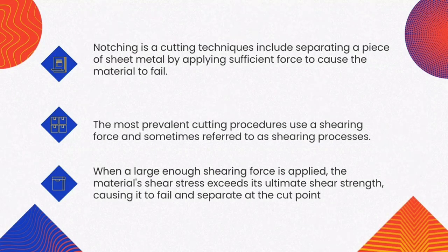A notch is cut inward from the edge of the material and then cut at a measured angle that is calculated in accordance with the application that requires the notching. Afterwards, the vertical cut that is made in the stock is made perpendicular to the edge of the material.